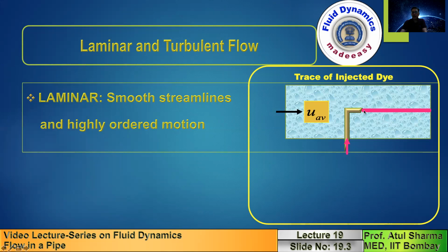So in a laminar flow, you can see that the dye remains horizontal, which indicates that a fluid particle in a particular horizontal layer is moving along its horizontal layer, and there is no transverse velocity. And in this case, when you have a uniform flow, this is a problem which corresponds to a laminar flow where you have a horizontal velocity. So in a laminar flow, the dye moves along a straight path, which indicates that the fluid particle moving in this horizontal layer remains in that layer.